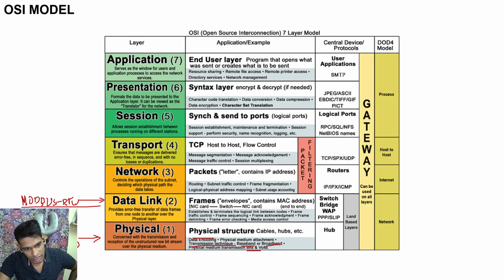See, without the physical layer, the RTU cannot work because it does not define the voltage levels, it does not define the data encoding or the baseband bit, all these things. It only defines how the frame should be made. Frame should have an address, should have so and so function code, and it should have so and so error checking codes. That is what is defined in the data link. And in the address, how the data is shared, that is also defined.